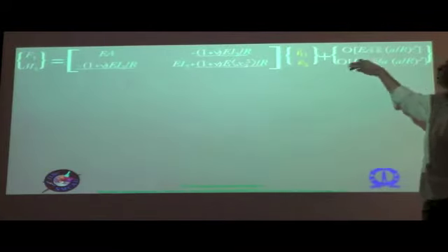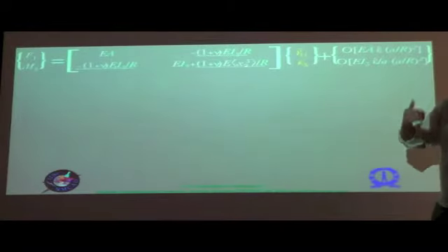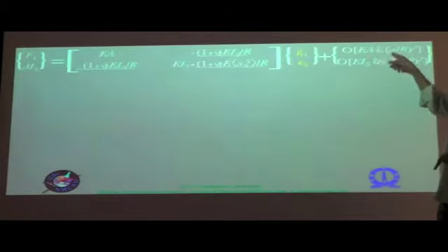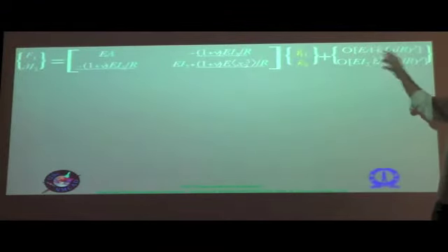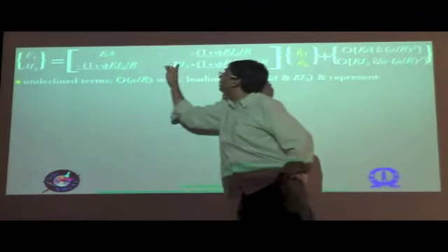Then of course it is also possible to determine from the orders of magnitude that we have what would be the next higher order of magnitude if it would appear, because we already have the orders of magnitude of each of the strain measures, the additional terms, and therefore of the energy, and therefore its derivative with respect to the 1D strains. From that we can estimate what the next higher order terms would be in terms of epsilon hats and A by R or A by L. The underlined terms are of order A by R with respect to the leading terms. In other words, they are smaller compared to whatever is already there.